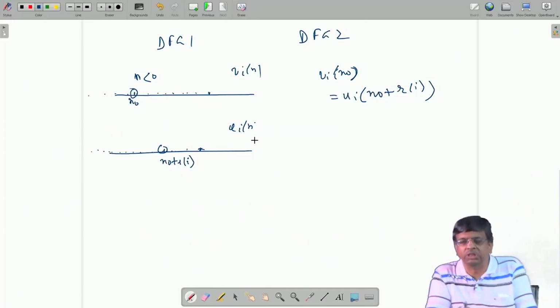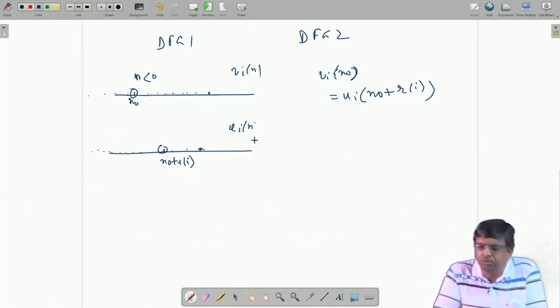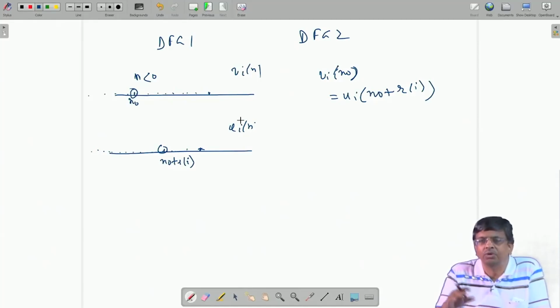Now, this is not just for theory, it is important that both the systems are cleared. They should not start with any other non-zero initial condition, because then only they will be equivalent. Otherwise, if the flip flops are carrying some initial data, that will create error in the system outputs. So, both have to start from zeros.